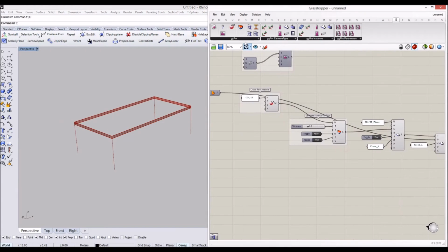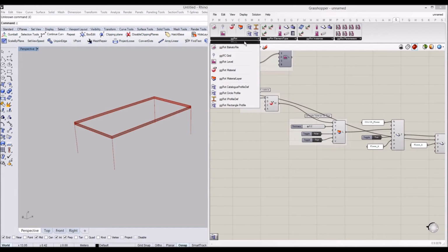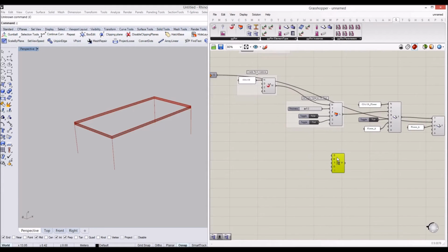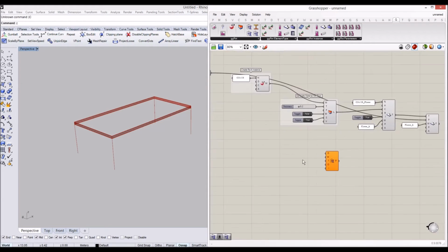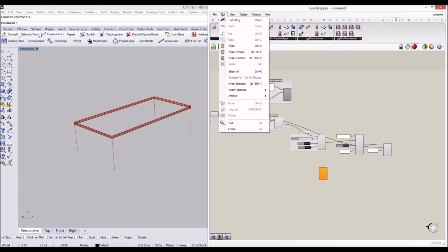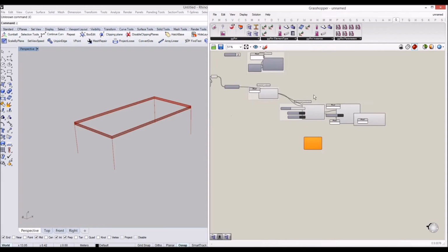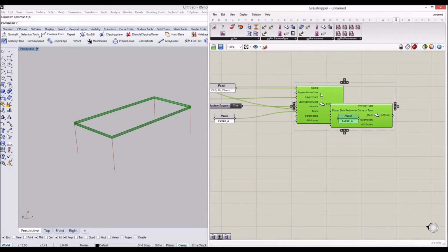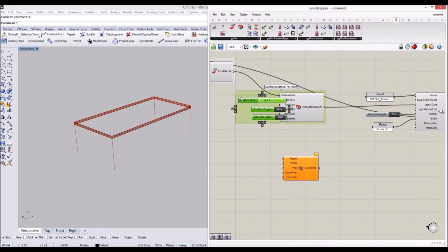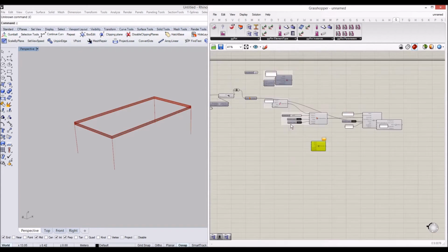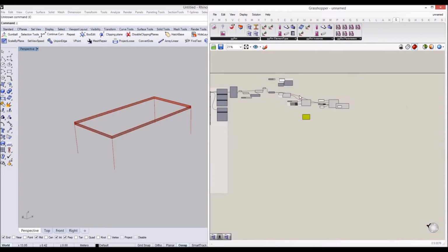So let's go to the GeometryGym Revit components here, and this time we'll use the Grasshopper GeometryGym Revit rectangle profile component. So we can define the depth and width of cross sections. Perhaps it's good to see the full name view to use GeometryGym. So I'll go to the view display. We'll make it display in full view, so we can see the information better for each component. Okay, a little bit of this, yeah, we can ignore that.